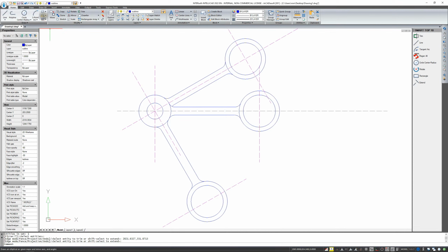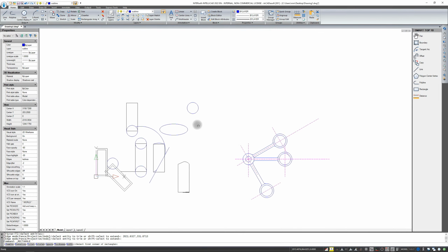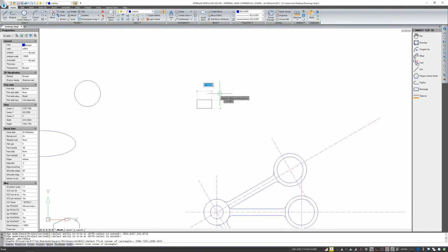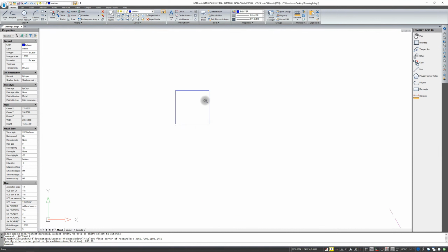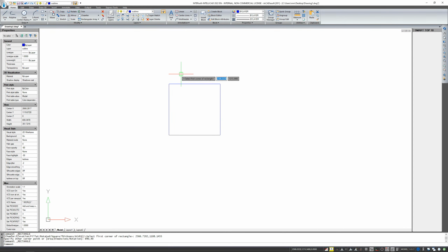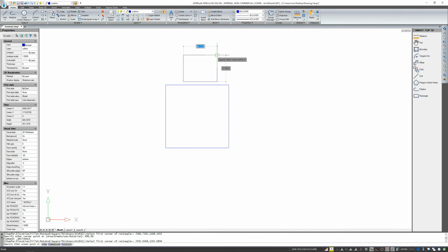I will choose the rectangle option. I will make the rectangle a square, but it still won't make much difference. Note that when I click on the first point, I simply specify the size, width, and height of this rectangle. Here it will be square, which is 90 by 90. I'm going to make this symbol for a table with chairs. And now I'll draw another square. But first, I'll draw a rectangle 45 units by 40 units.